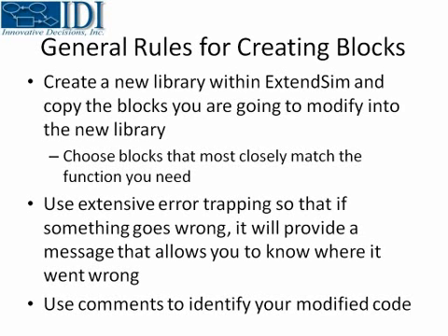And then the last thing I learned was to make sure that you use comments to readily identify, within the ExtendSim block, where you insert your own code, because chances are it will not work the first time. You'll have to go back and do some troubleshooting, and where you insert the code is going to be in multiple places in the block, which I'll show you in the upcoming slides. So it makes it a whole lot easier if you mark it clearly so you can find exactly where your code is.